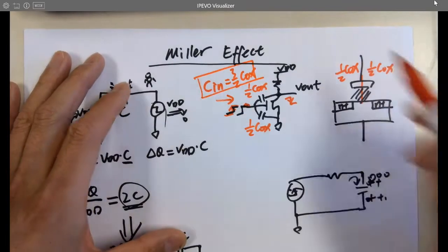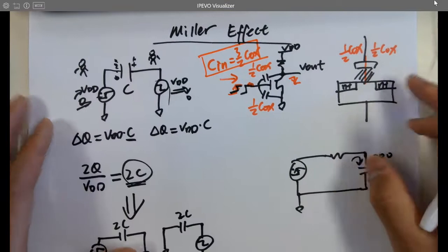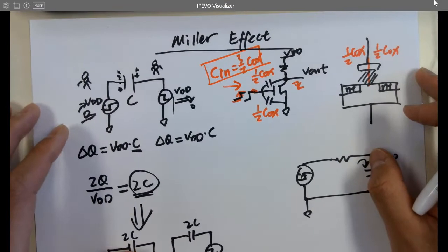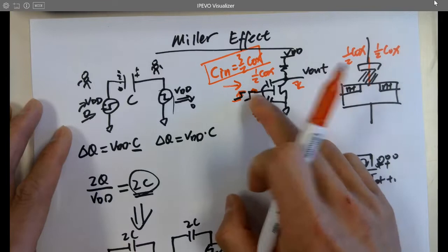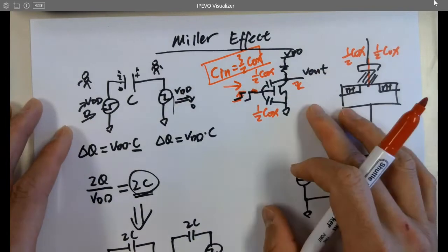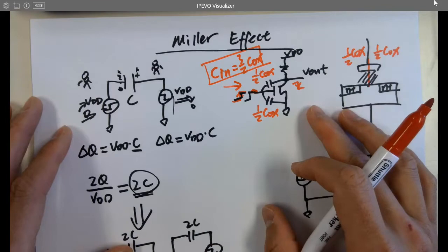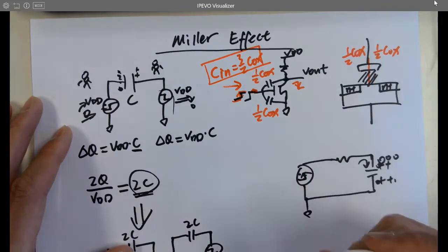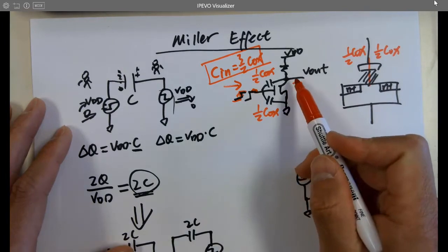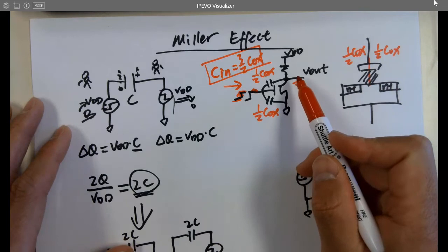It's important. It's not just for this class, right? It's important fundamentals of circuit design. Whenever you are calculating capacitance, you have to consider that Miller effect. It's everywhere, not just here. So we pay attention to that if both sides are receiving a charge.